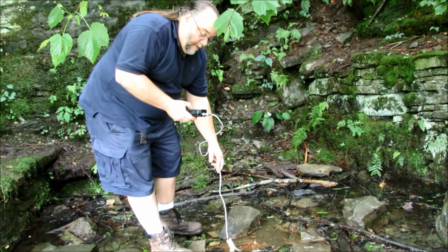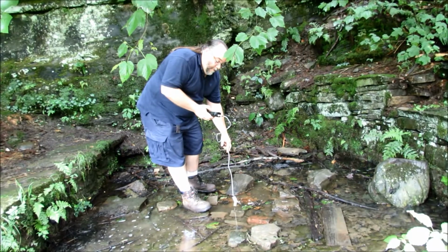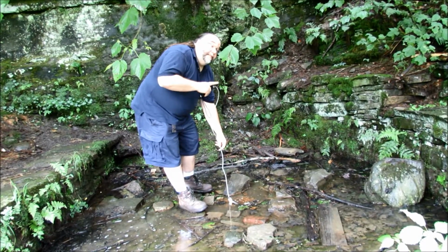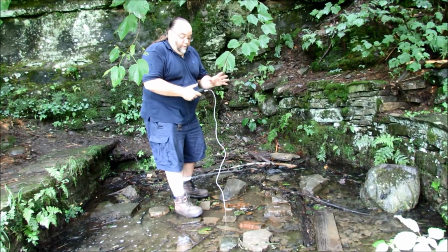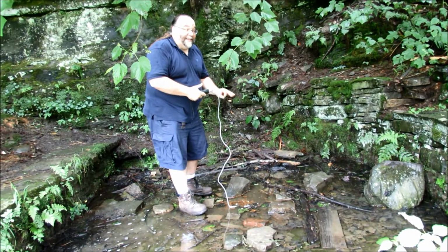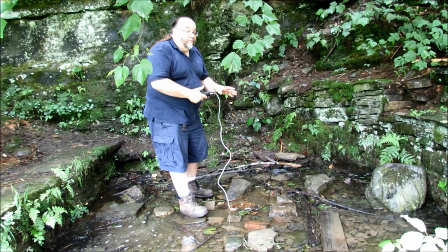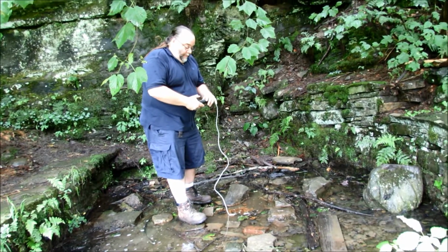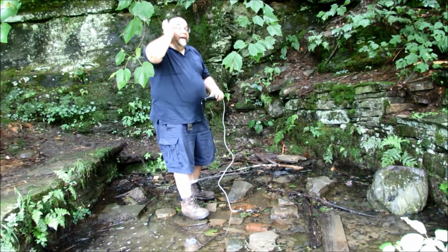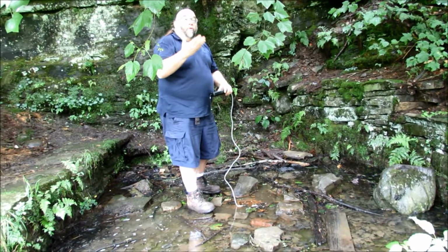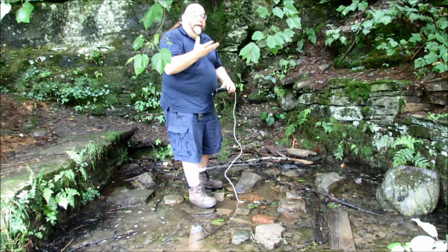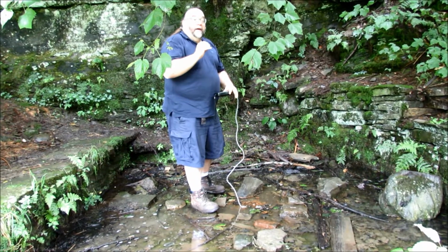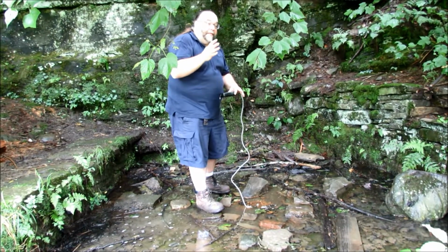So what are you getting here? The pH is going to take a while to go down. For now, over at the stream, we had a conductivity of 70. Okay, the conductivity here is 6,620. Wow. What does conductivity mean? Conductivity is the ability of the water to carry a charge. The more stuff dissolved in the water, the higher the conductivity. But it's not always the same.